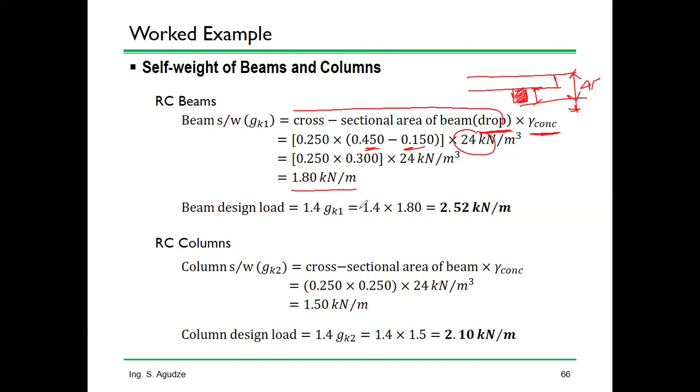And remember, anytime we are dealing with beam, column, the answer should be in per meter. But if you are dealing with slab, the design load you calculate, first calculate in per meter square, and later you can get your answers in per meter after doing some other calculation. Okay, so because again, this one, we know we have dead load and imposed load.